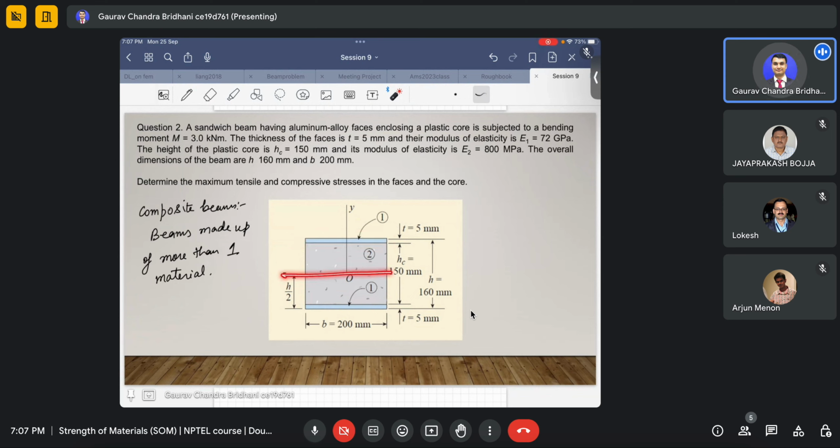Okay, so you can see that this material is being put in a way which is parallel to the z axis. Always remember, if anything has been added to a beam parallel to the axis of its bending, because this is the axis of bending, then its main contribution is in the bending, so it will resist the bending. That is why this has been introduced here.